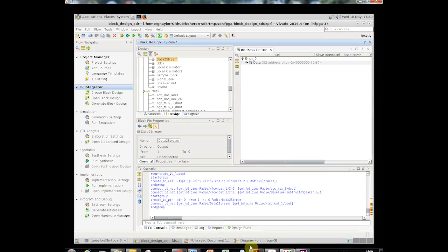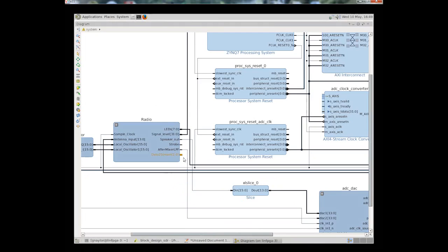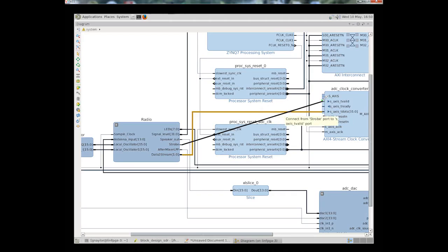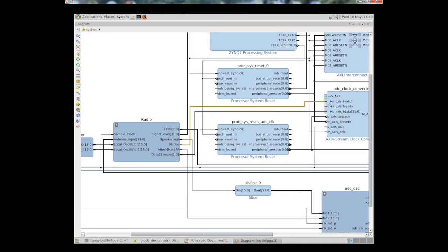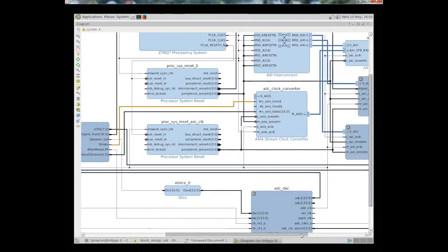Okay, so go back up to here. This is data to stream. The auto width working out bit hasn't clocked onto the fact that this is a 32-bit value, but we can check that later. But it should be a 32-bit value when we send the data input. And the T-valid, we're going to use the strobe to clock that at 32 kHz. We're not going to bother reading T-ready, we assume that it's ready.